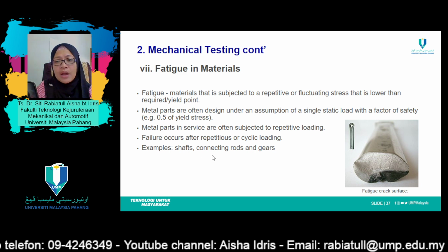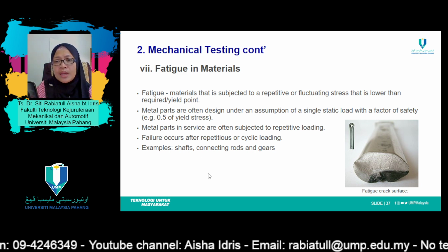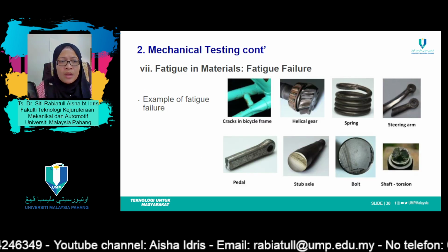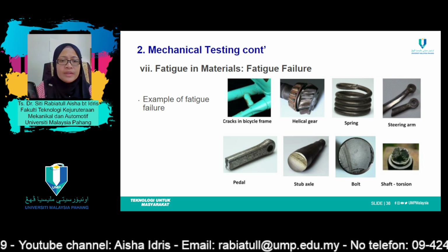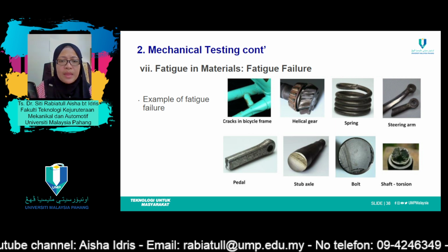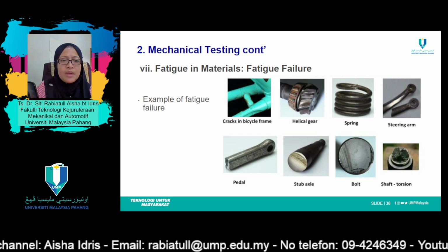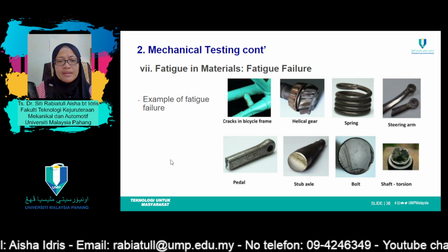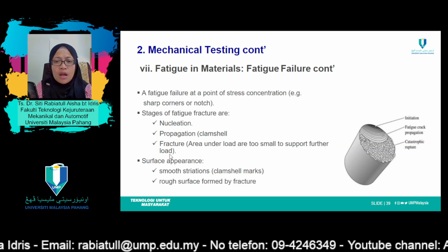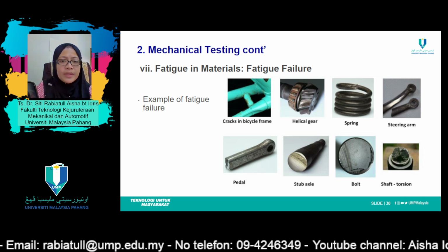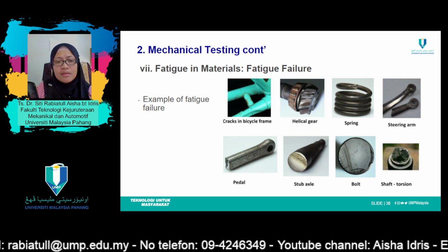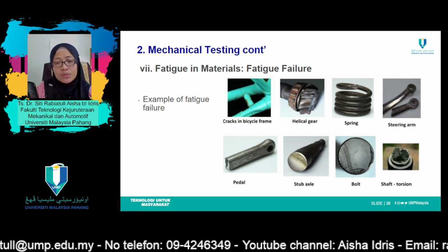Examples are shafts, connecting rods, gears, and so on. Usually, the purpose of fatigue test is to determine the lifespan that may be expected from a material subjected to cyclic loading. However, fatigue strength and crack resistance are commonly sought values as well.